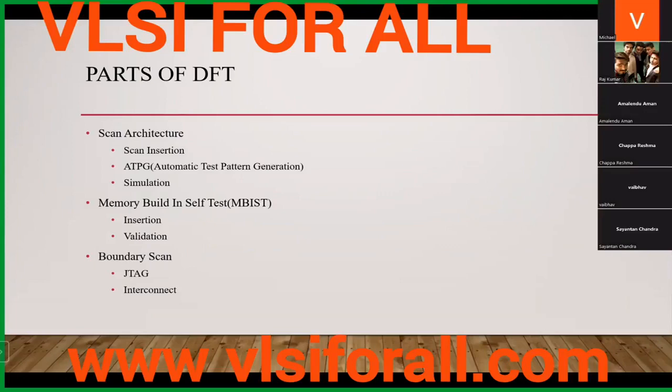It's automatic test pattern generation by different EDA tools. There are different EDA companies providing EDA tools for pattern generation, and then we need to simulate those patterns on different simulation tools available from Cadence, from Synopsys, and from Siemens right now. That was Mentor, but it is acquired by Siemens. So those are actually the scan part, and people generally have a scan team, and we have people who are doing the memory testing. We call it MBIST.